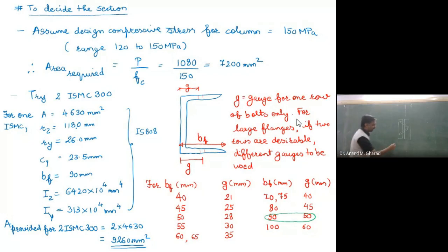There may be another case where the lacing plates are overlapped and the connection is something of this sort. Such a case is also acceptable. Such lacing patterns you will come across, but most of the time, if bolted connections are provided, depending on the load carrying capacity, the number of bolts evaluated is only one.